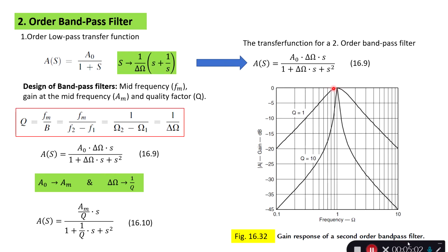So it is easy to build in a gain factor at this specific frequency. So we have to define whether it should just be a gain of 1, or whether we need some gain at that frequency. The quality factor, remember, is how steep it is, meaning here at minus 3 dB, what frequency range should we allow, or can we only allow this amount of frequencies passing through the filter?